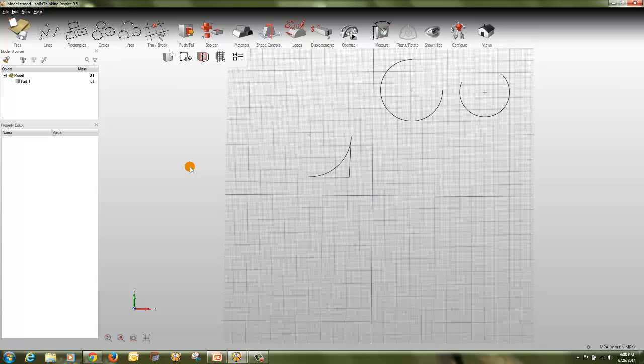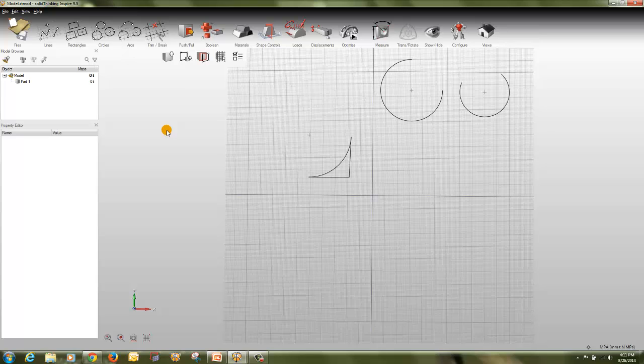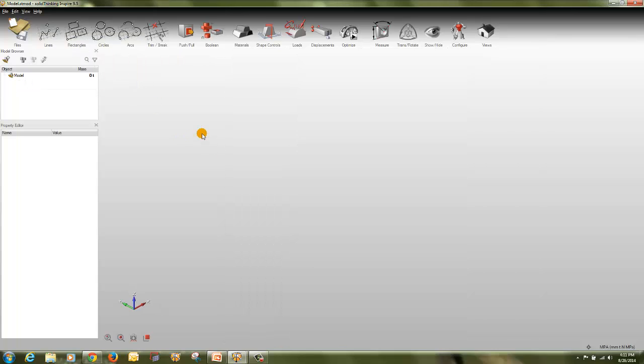So this is the third option in which you can edit the arc and the other options. So now let's talk about some sketch constraints. I'll have the new file. So we'll see about the sketch constraints. When sketching, you can apply geometric relationships such as tangency, perpendicularity, etc. to lines, rectangles, circles, and arcs using the sketch constraints.